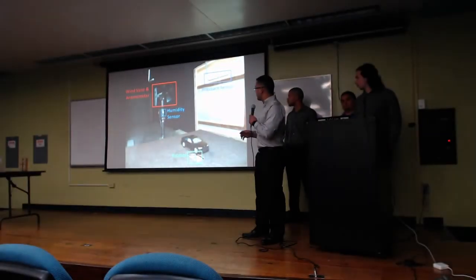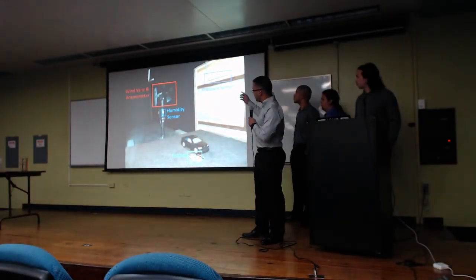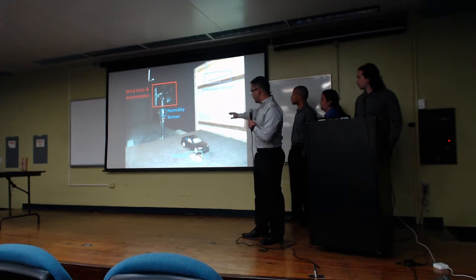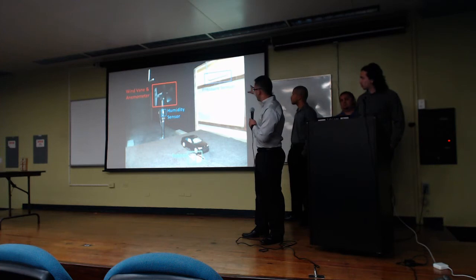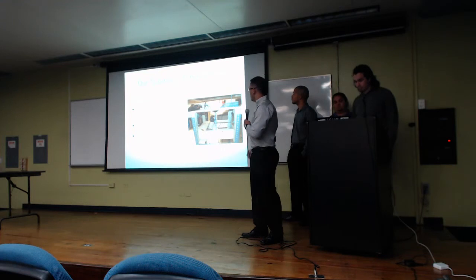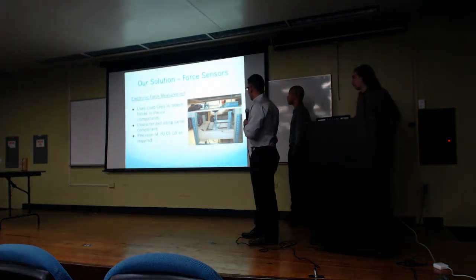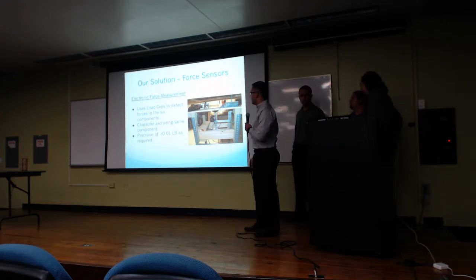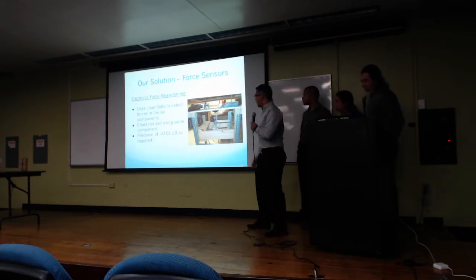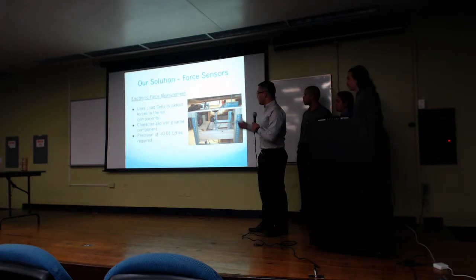This is the current sensor setup of the wind tunnel, where we have the wind vane, anemometer, and humidity sensor at the center above the car, the object that we are measuring, which is placed on the balance at the back, which measures the forces, and the pressure points that we can locate everywhere in the tunnel. This is the new balance, which is basically a modification of the old one, but has load cells, which will measure the axis on a new axis here, which is the zero axis, and have a precision of 0.1 as required by the client.